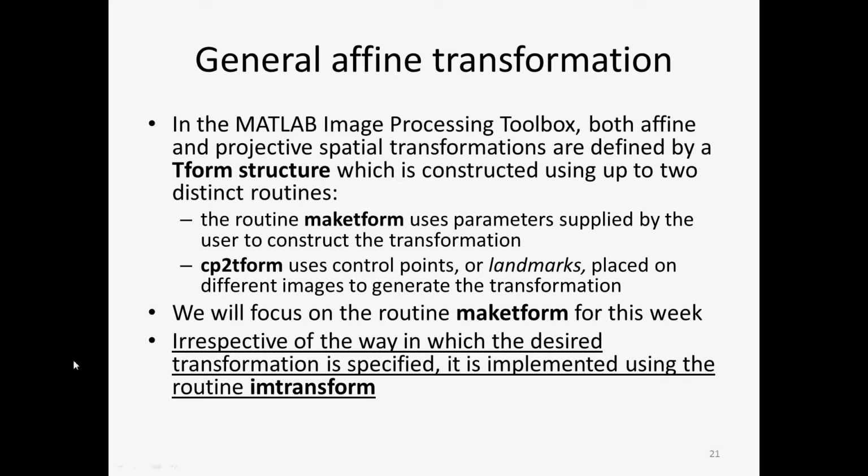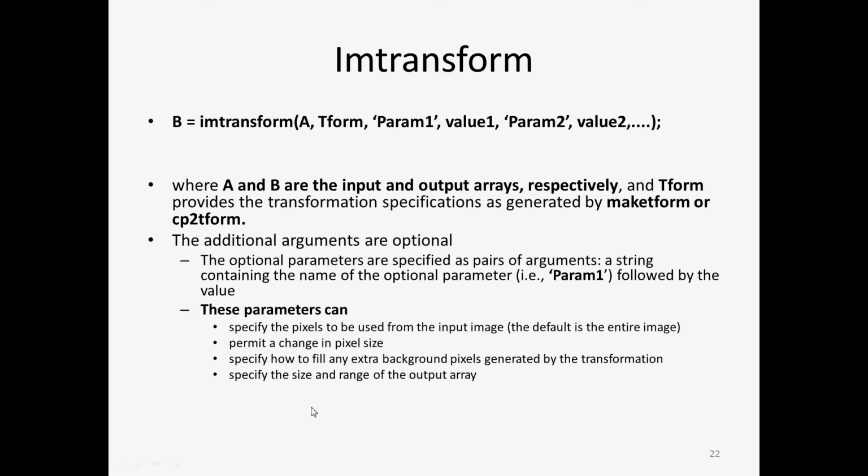The most common way of doing it is using imtransform. If you just type help imtransform into MATLAB, it will explain how imtransform works and all the parameters you need to give it, like the input and output image, and the values of the parameters you want to operate.